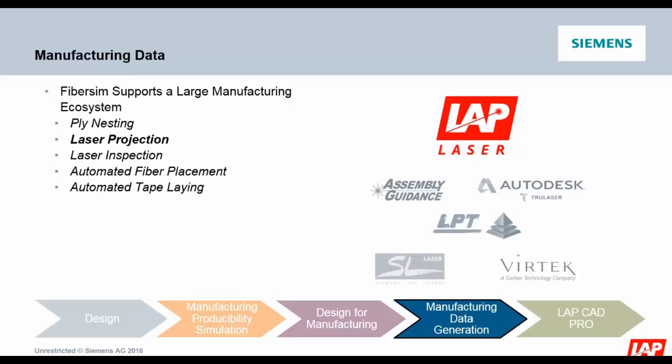Then for validation, the proper order needs to be communicated through the data from engineering to manufacturing. That should include things like ply names and sequence, and the data should be projected at the proper location and at the correct height in the stack up. Parallax error is important. We've seen it time and time again.